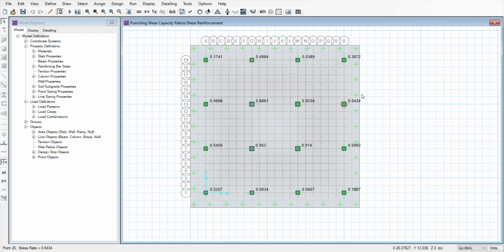Next, after drawing, we have to assign these properties. After assigning the soil properties and loads individually applied on each column, because the load for punching shear changes, and the load also changes for every column because of the cross-sectional changes, for the 4 columns in between these are 600 by 600 and the extreme columns are 500 by 500 columns.